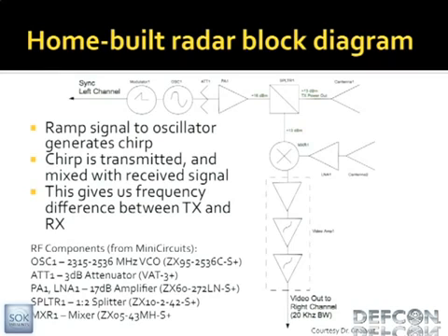There's an attenuator, power amplifier, which just makes the signal louder or more powerful. That signal gets split, and one of the copies gets transmitted out by one of these dishes here, coffee cans, sorry. The other part of the signal goes to that mixer, and that's what I said before was the local oscillator for that mixer. So the signal gets sent out by one antenna, gets reflected off of whatever, and then comes back and the other antenna gets amplified again because it's going to be really, really weak now. Remember that 1 over r to the 4th thing I was talking about? And then it gets mixed with that known signal.